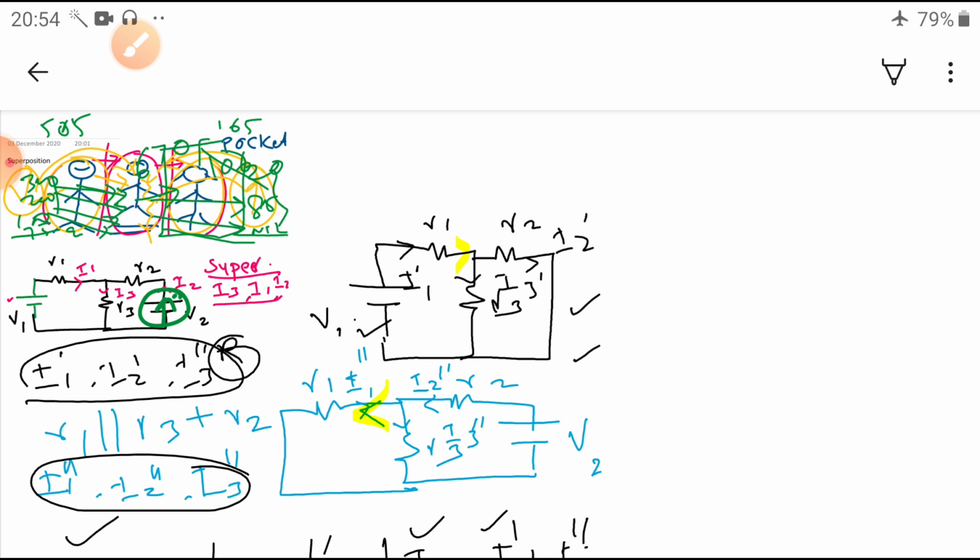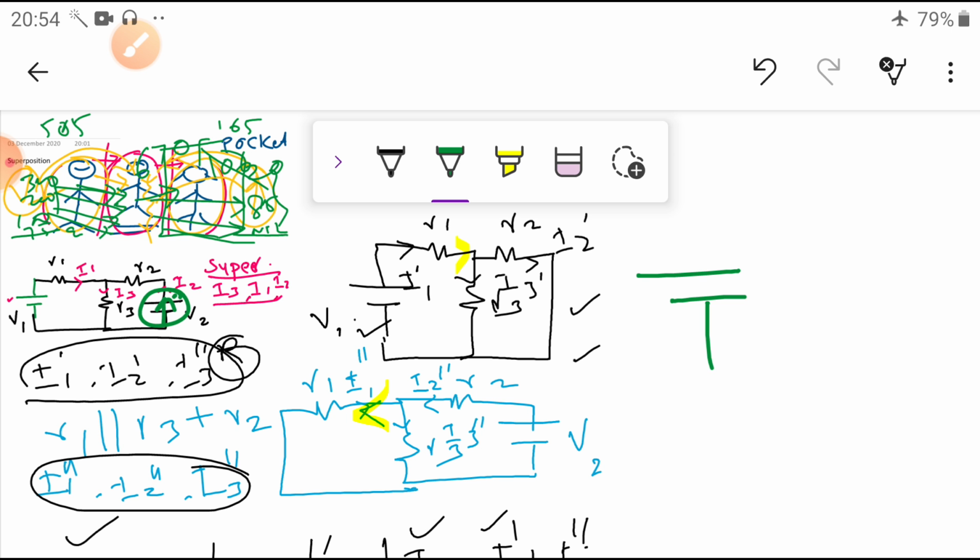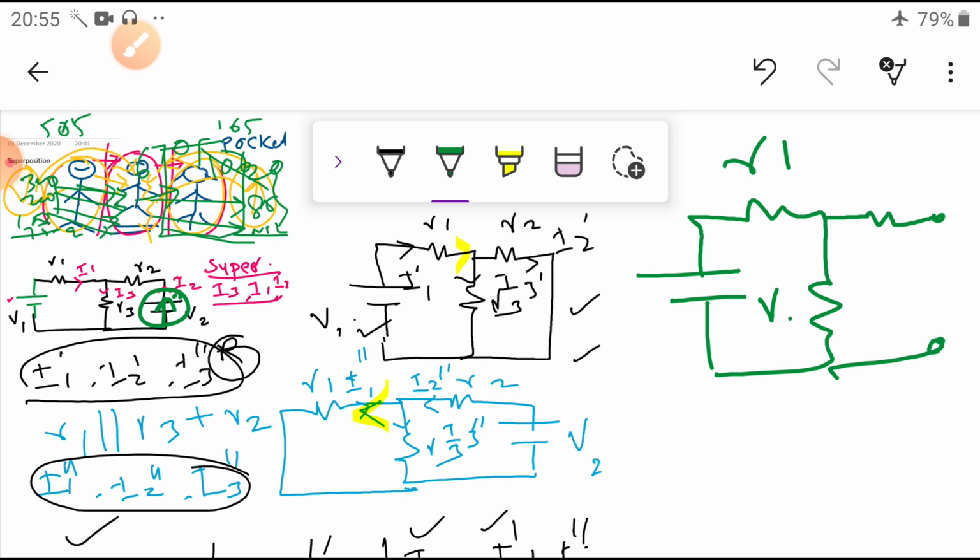So, here this circuit is simply, this is a source, this is a terminal. Now, this is opened because the current source is not shorted, it is open. Then what will happen? R1 and R3 are simply in series, then V1. Then find the current influence of this one, a simple circuit.